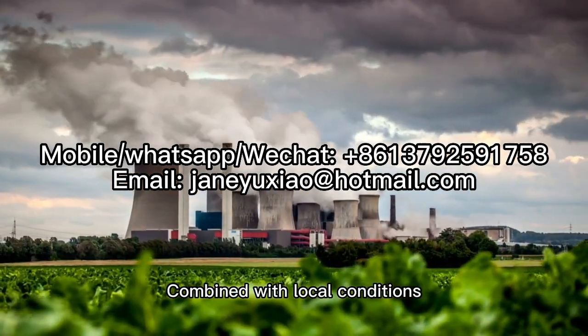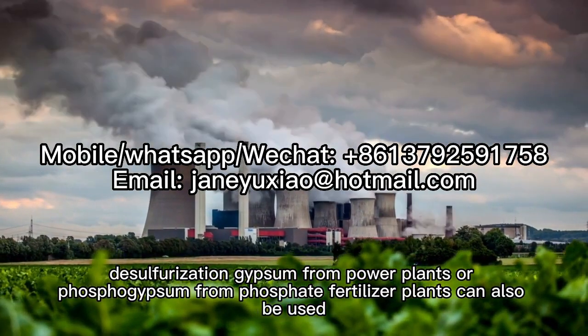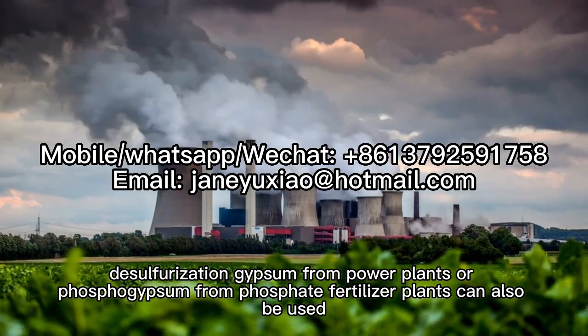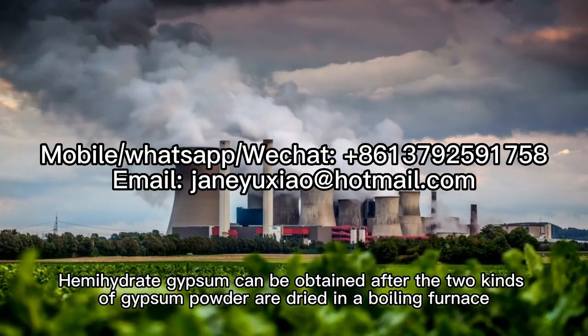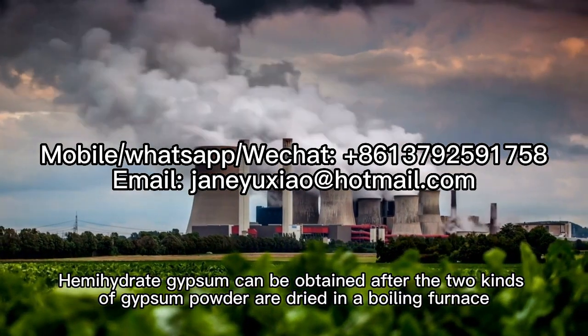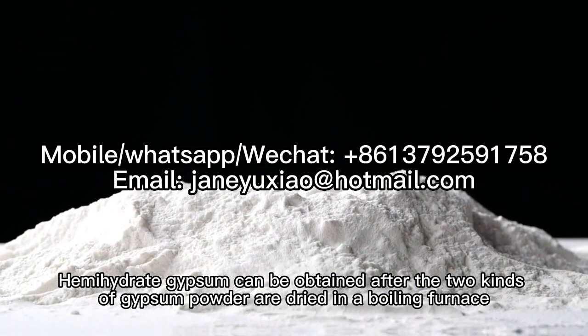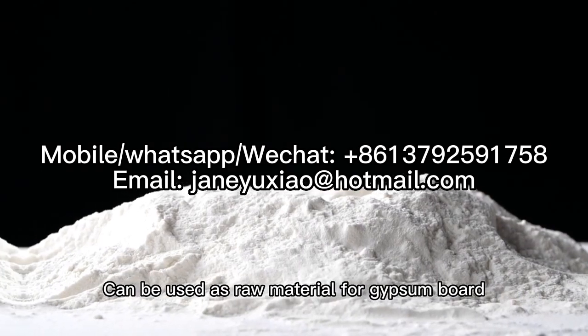Combined with local conditions, desulfurization gypsum from power plants or phosphogypsum from phosphate fertilizer plants can also be used. Hemihydrate gypsum can be obtained after the two kinds of gypsum powder are dried in a boiling furnace, and can be used as raw material for gypsum board.